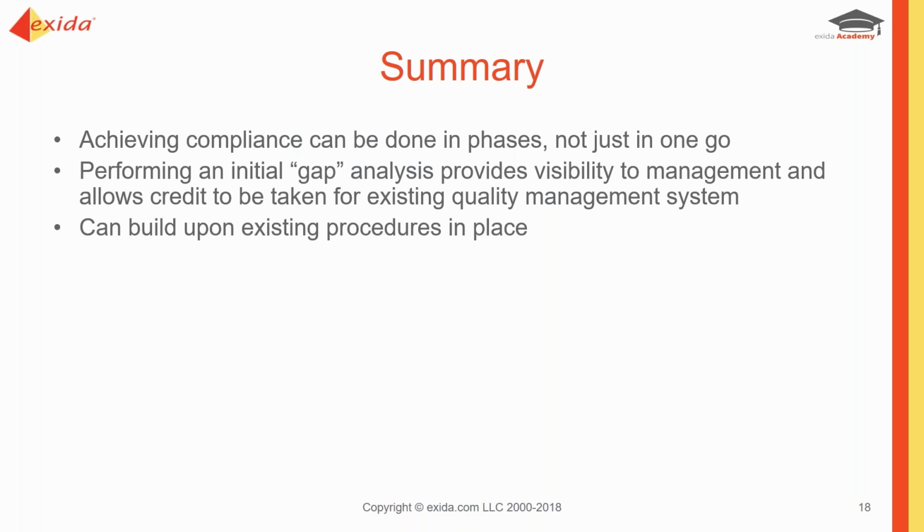So we have a functional safety management plan, a document that covers that. We can show that to any auditors. We can refer to the relevant procedures. We have evidence that those procedures are being followed and are working. And so we have visibility.